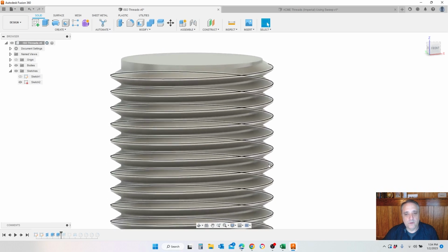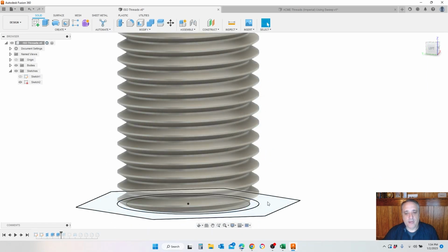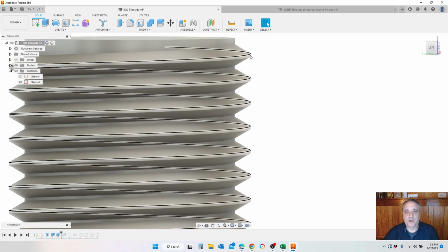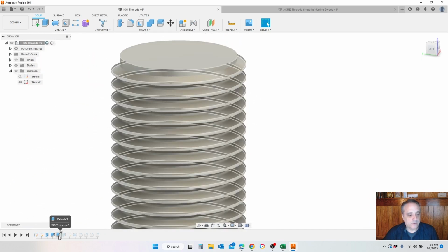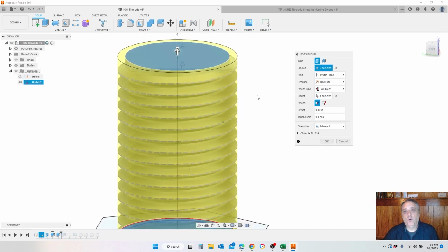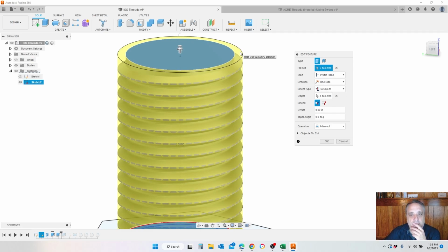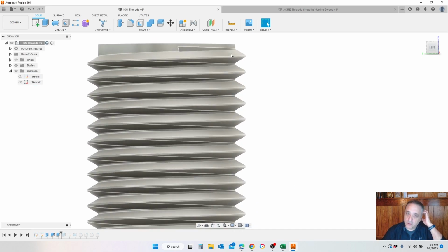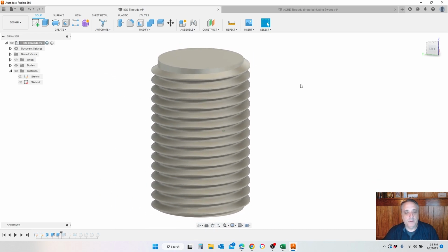The next thing we end up doing is an outside cut of this feature, flat side. So let me just show you how that looked. Edit feature. Basically, I did the outside diameter one, and I made it as intersect, so anything intersecting with it would be kept. So now we have our beautiful thread shape. And then I'll show you how these parameters change, because I had already chosen some of my dimensions.